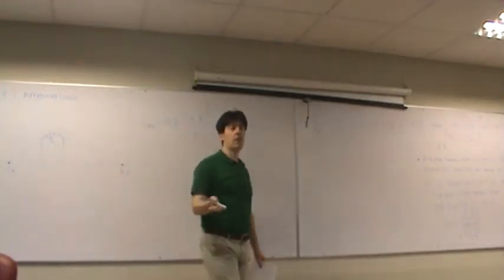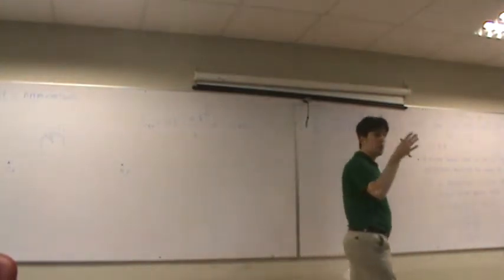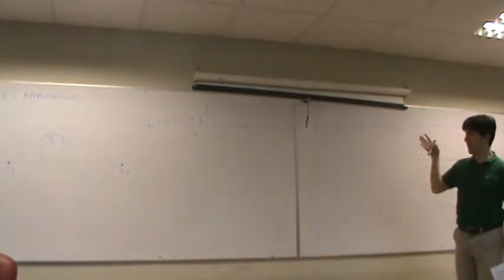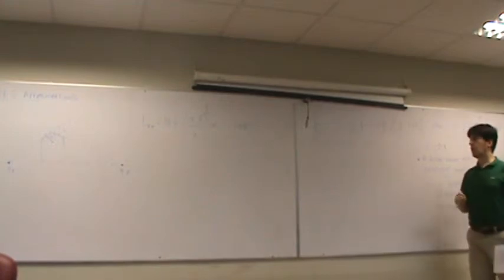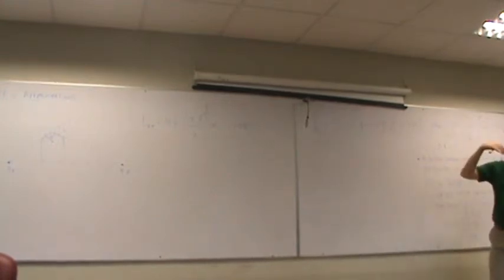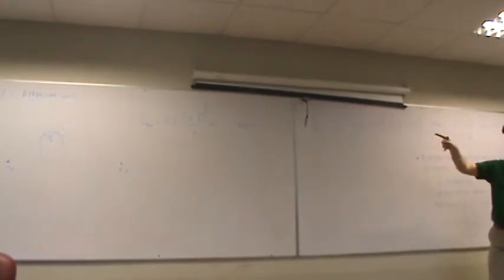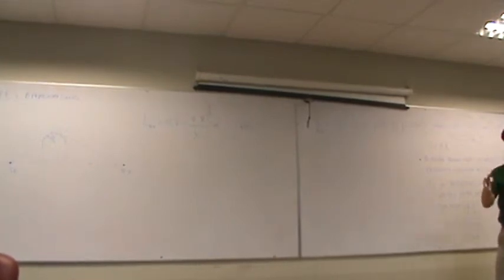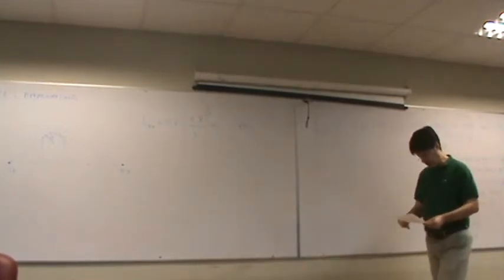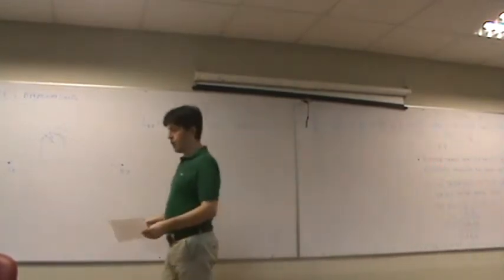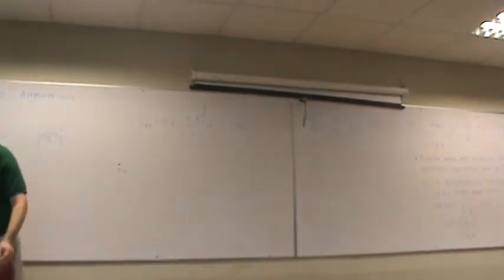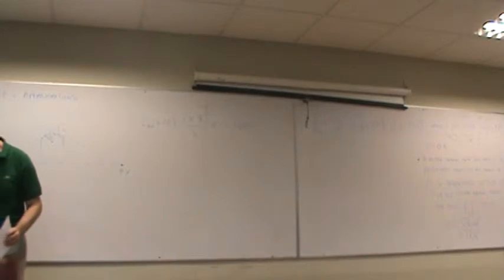So if you have the geometry, you calculate the losses due to knife edge blockage, and on top of that, you add those extra losses due to the round shape. The round shape, unfortunately, introduces stronger losses than sharp shapes.